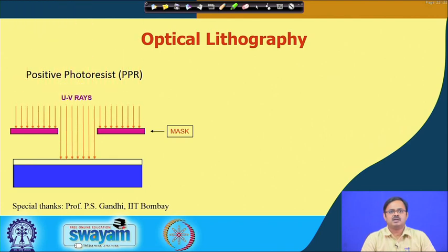I am showing a 2D structure or 2D cross section. Now let us put UV rays. Where the mask material is, it is going to block the UV rays from passing through it, but where I have a cutout, whether it's a hole, an orifice, or a slit, the UV rays pass through that cutout and fall on this photoresist material. As the UV rays fall on the photoresist material, it undergoes certain changes in properties, and which later can be removed.